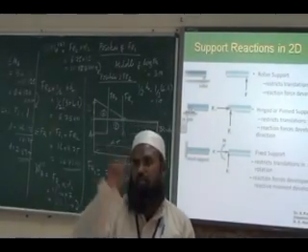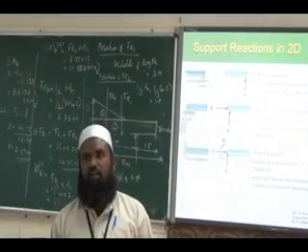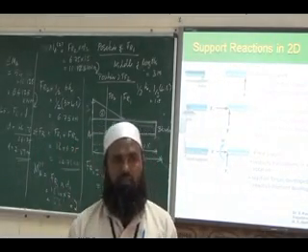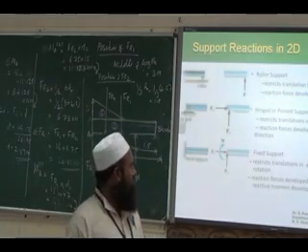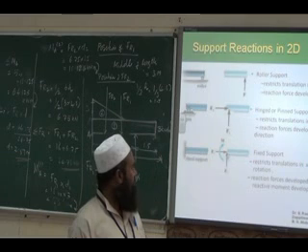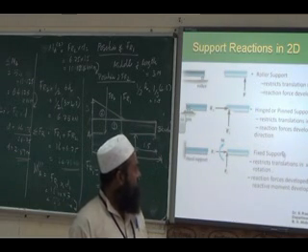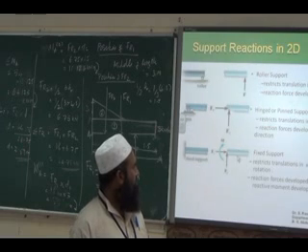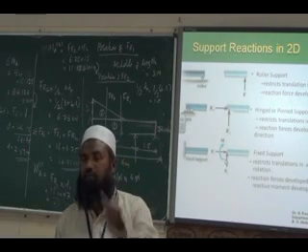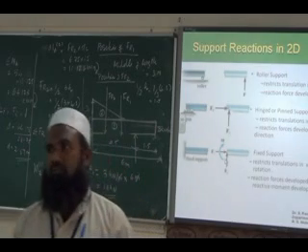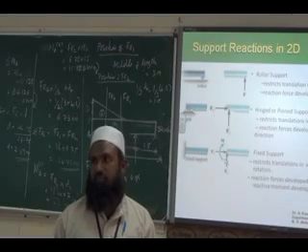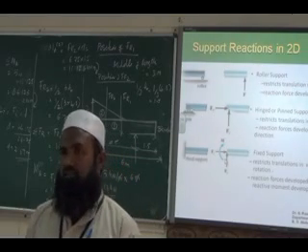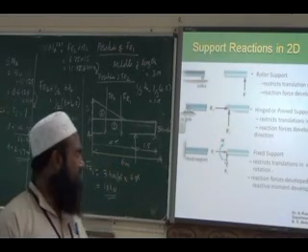Okay, arbitrarily we put it as counterclockwise, but it is not exactly true. It should be counterclockwise only or clockwise only. Just the moment is developed. Okay, a reactive moment is developed, and two forces are developed. To account for the direction of the force, we have to depend on the applied forces. That we will see here. Sense of force and sense of moment, we cannot decide now. There is no applied force shown.